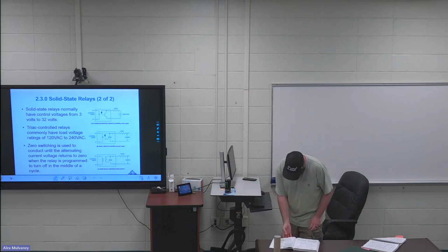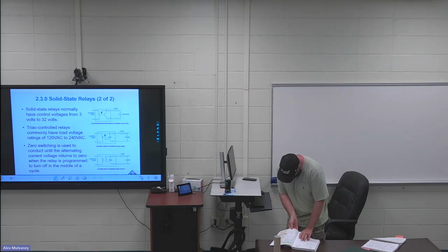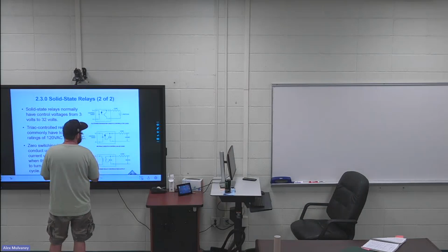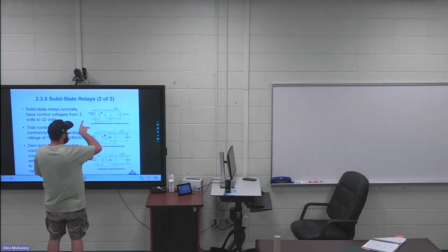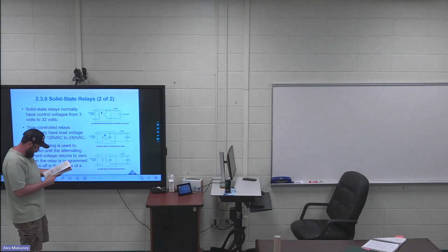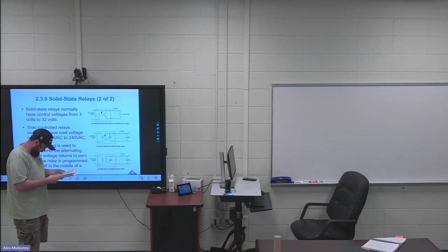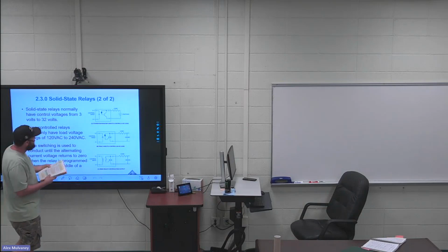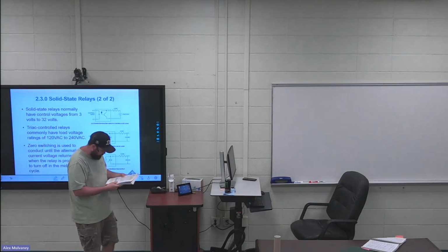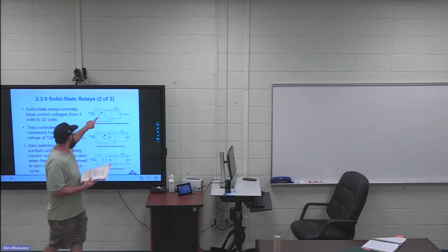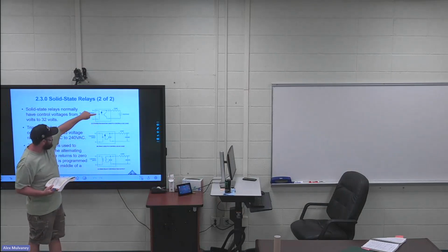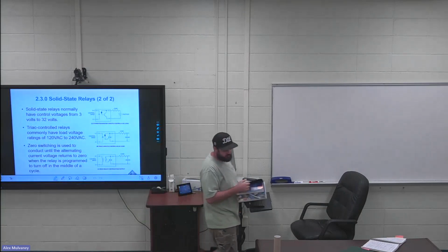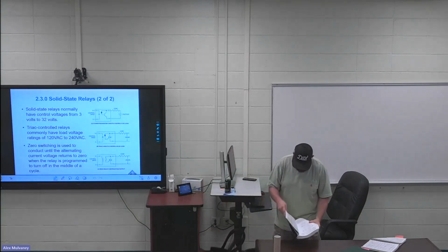In this DC circuit, a power transistor is used to connect the load to the line as shown in figure 13A. So that's my line side over here. This is an opto-isolated relay with a light emitting diode. So your light emitting diode is right here. So this is an opto relay. Your light emitting diode's right here. So there's not anything that actually moves. Something in the solid state relay just turns on a light essentially.